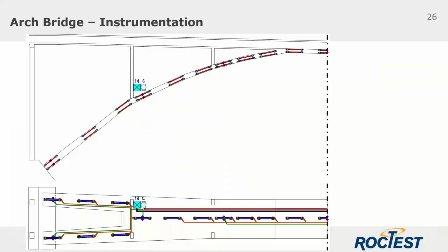Right, here we can see again a parallel topology that is used in the vertical plane only. So since the forces are typically transferred from the superstructure to the arch via the columns, each segment between the columns is instrumented with 3 cells of parallel sensors.